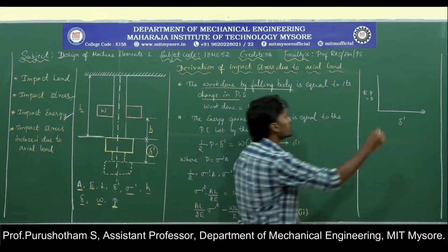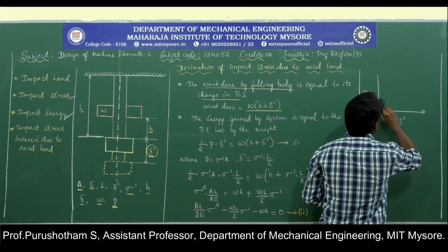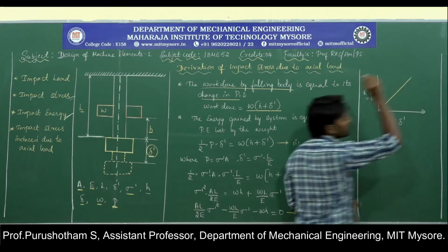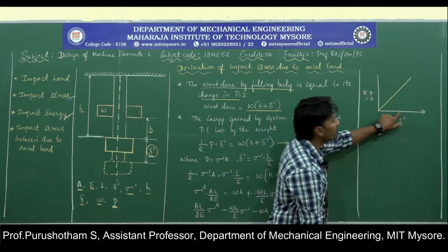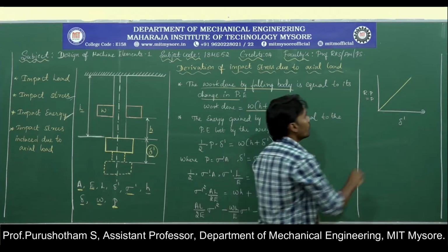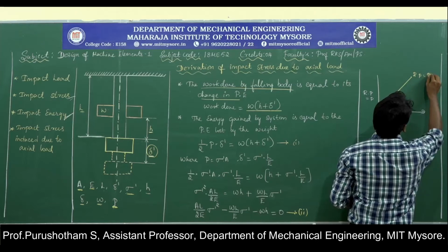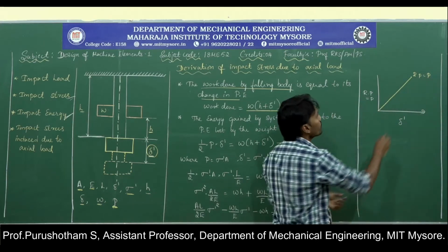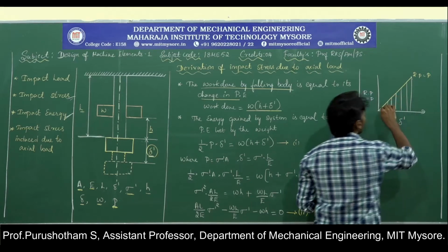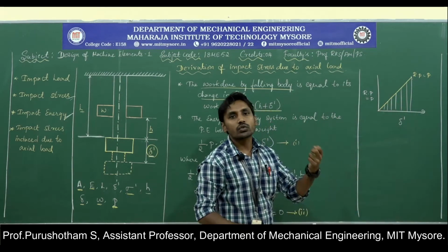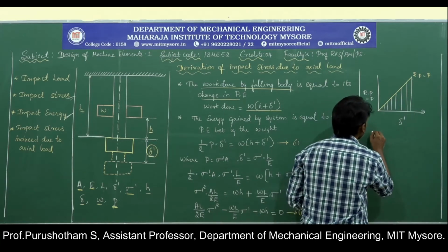which is equal to the applied load P. So when you apply a load, the resisting force develops in the body, and in the meantime the deformation also occurs. As we know, the resisting force is equal to the applied force. So if you take the area under this curve, that means the body stores some energy here. This energy is called strain energy.